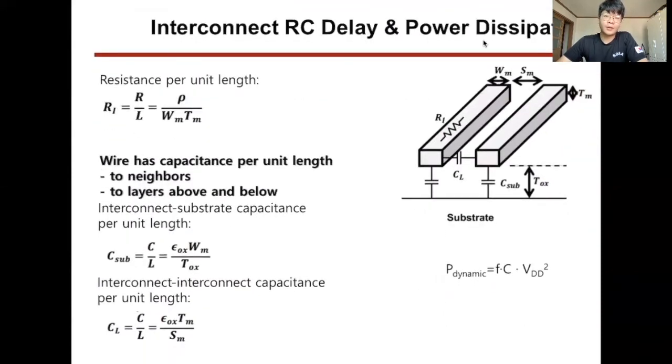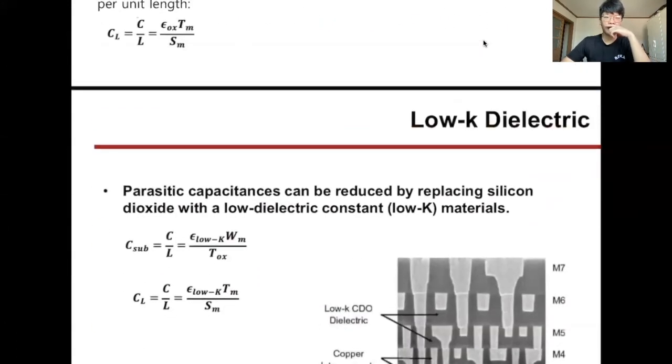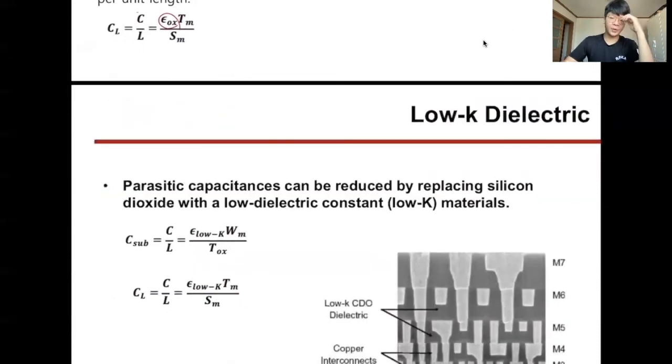There is a parasitic capacitance between two metal lines, and between the substrate and the interlayer depositions. To prevent this parasitic capacitance, we electrically isolate each line, except for the via, with low-K materials like air. It is very important for electrical isolation. Like air, we say lower epsilon here because it is a low-K dielectric.